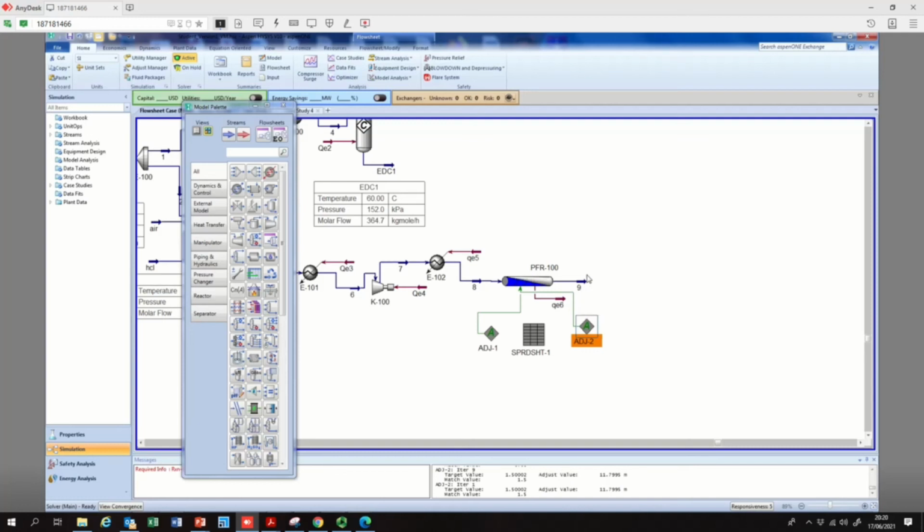And then we also learned how to add reactions in a set, and then we also created a new set where we added a new reaction, conversion reaction, and then we know how to add a CSTR, we know how to optimize the residence time in the CSTR, and then we realized that the literature value didn't help us, so we deleted the CSTR and then we replaced it with a conversion reactor and so on. So these are the things you should keep in mind. So I think you might have learned already a lot in Aspen HYSYS, some of the features available in the HYSYS.